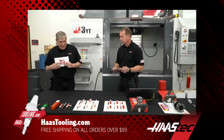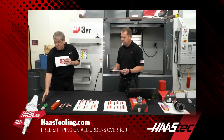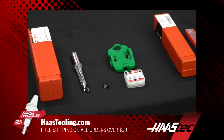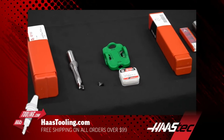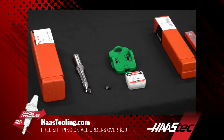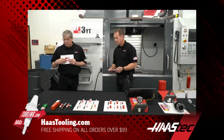They kind of bridge the gap between the solid carbide drills and the larger insert drills. And the cool thing about these is that you can get one drill body and put in a couple of different insert sizes, so you can drill different size holes with the same body just by changing the carbide insert. We have 8 different seats, or 8 different bodies, and 18 different inserts available that fit those. So that gives you an idea of how many different inserts are for the different bodies.